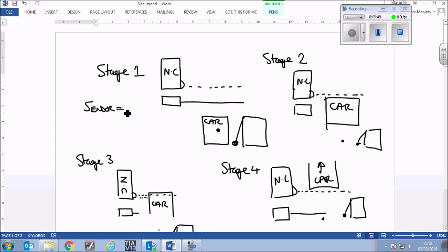In stage 1, the sensor is displaying a 1, as in it's on. Okay, because it's wired normally closed, so when there's nothing in front of it, it's in a closed state, and therefore provides a 1. If you think about it of push buttons, if you have a standard push button like this, and if you imagine the box on the far side, you write a 1 in it if a voltage arrives in, you write a 0 in it if no voltage arrives in. In this state here, you would write a 0, okay? Because it's normally open and it hasn't been activated.